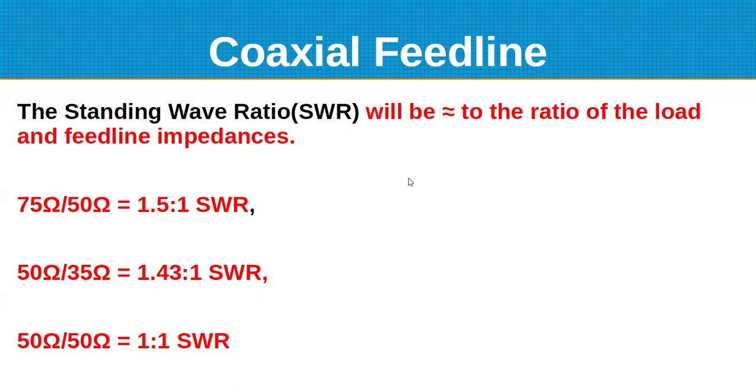Okay, well, you could use it. Actually, it would be a better match to a half wave dipole, but you'd have to have a matching unit, or tuner, at your transceiver end to match it to 50 ohms, which is what your transceiver wants. But it could be a better setup because it's going to be maybe a little lower loss, and you're not going to have as big a reflection coming back.